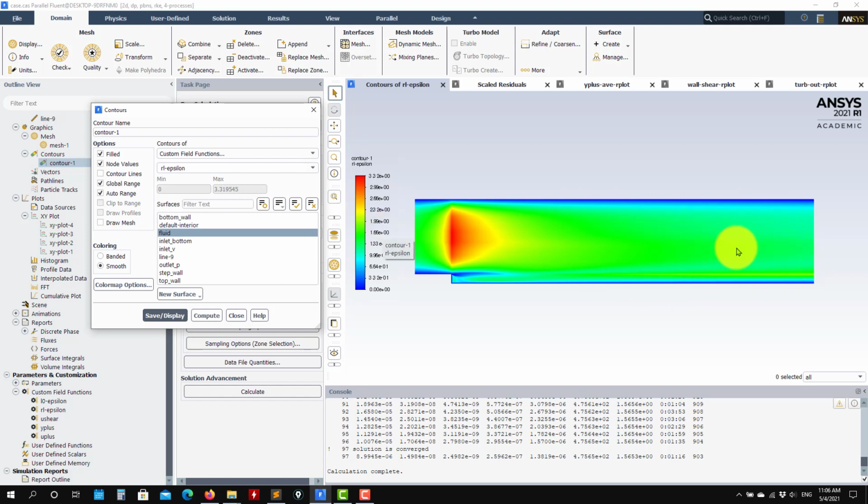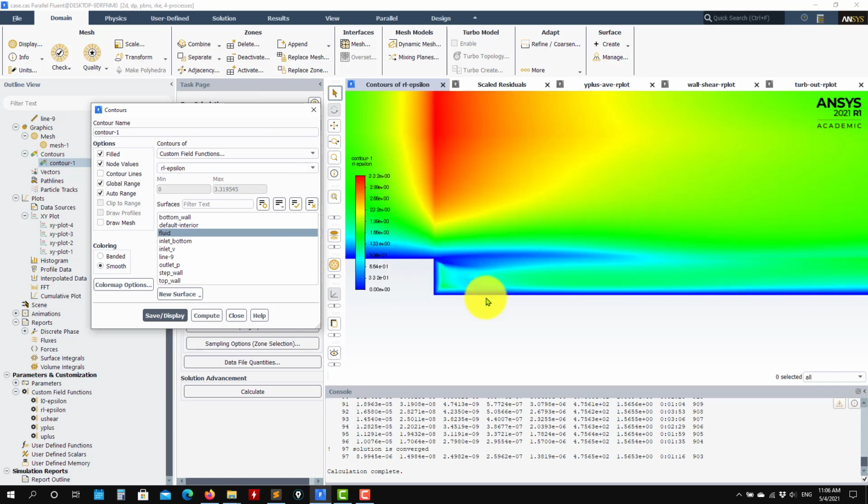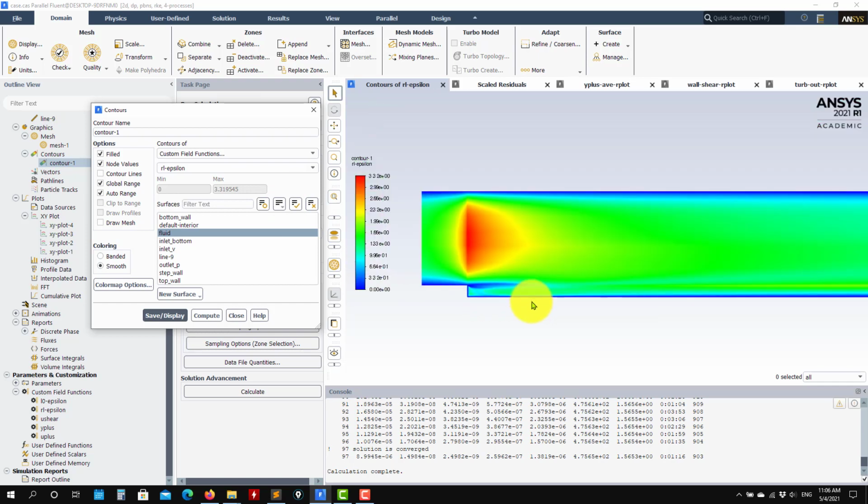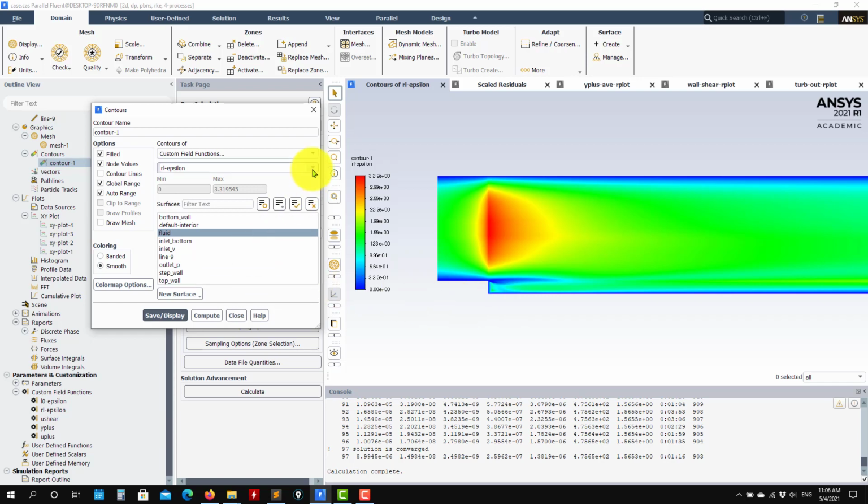So see that this is probably telling you that you need to kind of double your mesh, but remember, you need to look at the core, okay? This is the indication at the core of the flow, okay? Close to the walls there, don't pay attention, because there you are in the velocity gradient, okay, that is influenced by the velocity gradient. So likely you will need to double your mesh to capture better there, but this is a rough indication, but it's better, like I say, better than nothing or just going trial and error.